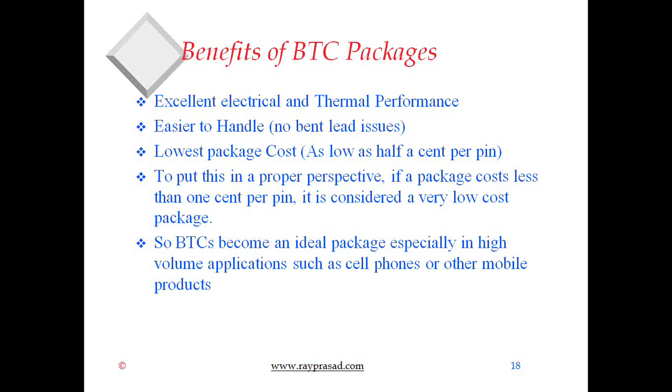And it's very easy to handle. Even if you drop this package on a floor, it doesn't have anything. There is no issue about bent leads. That's the main issue in QFP, because you can breathe on it. Depending on how hard you breathe, you may bend the lead and you got a defect. You don't have that kind of problem with the BTC.